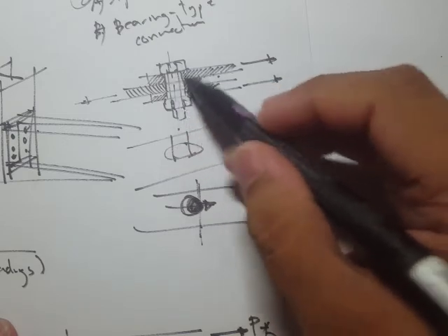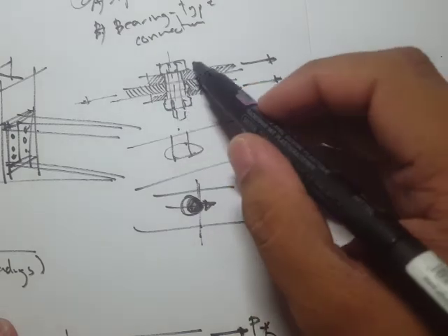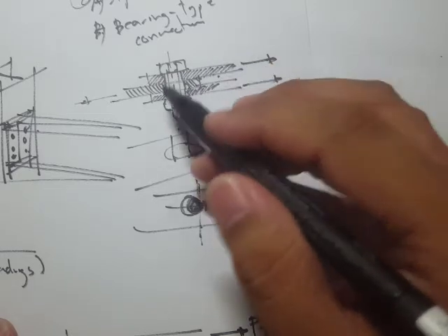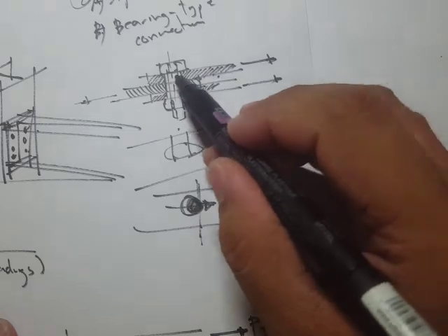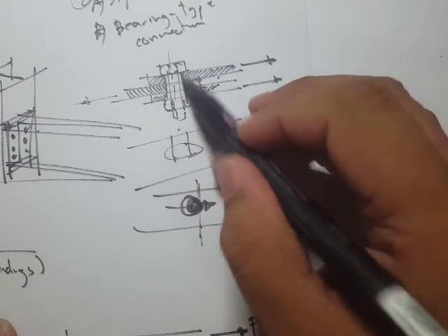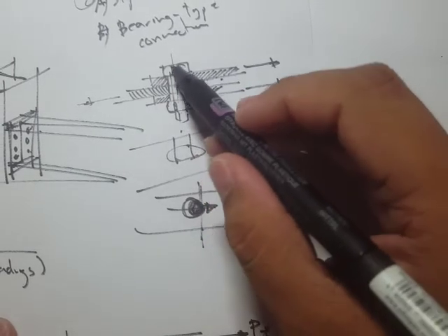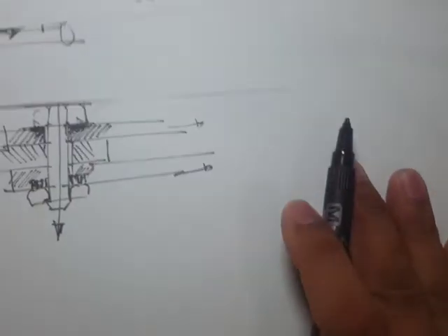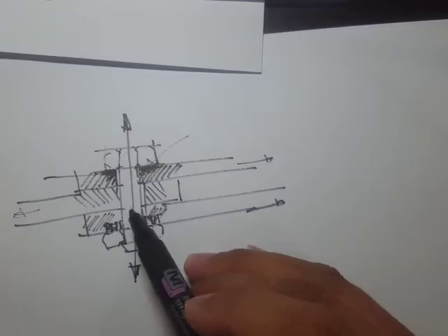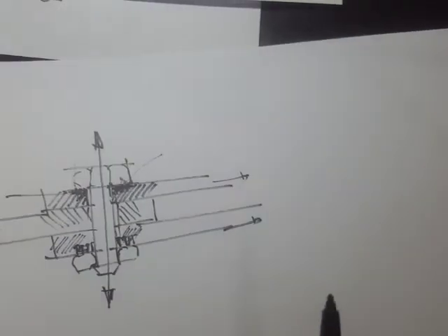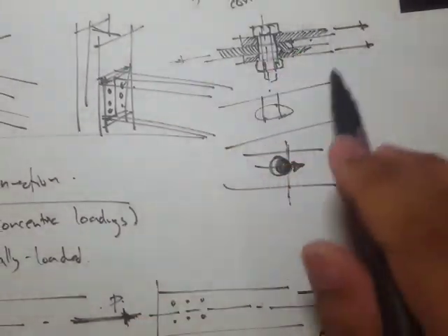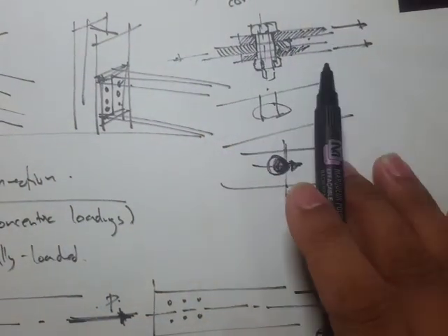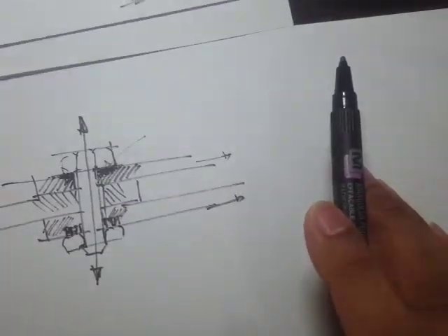Of course you are, and you should be tightening the bolt, except that the design intent is to transfer the forces by bearing here, and the bolt is in shear, whereas here the bolt is in tension. Okay, so I'd like to highlight this. It's because we will only consider this type of connection, the bearing type connections and simple connections.